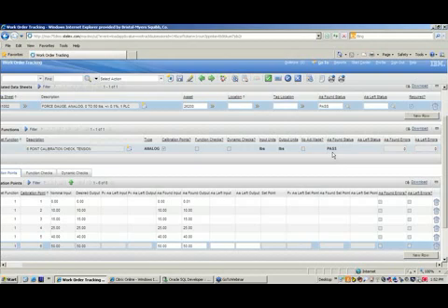Okay, so in entering all the values, when a technician completes all his as found inputs and outputs, based upon those entries, and if every value is within tolerance, the system will update the as found status accordingly. And because all the values here were within tolerance, this first as found pass has passed.